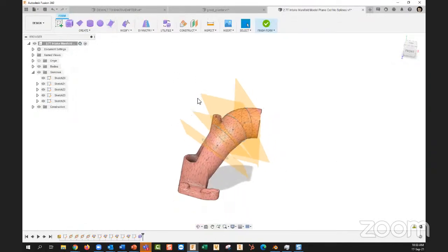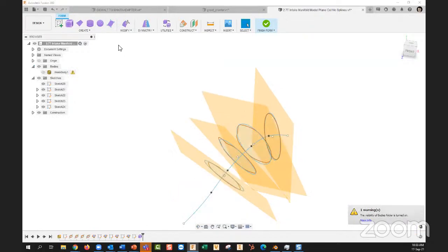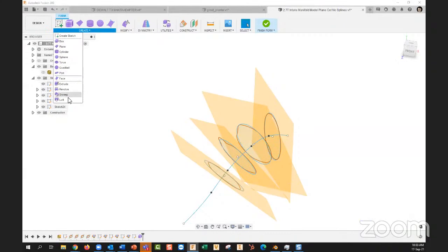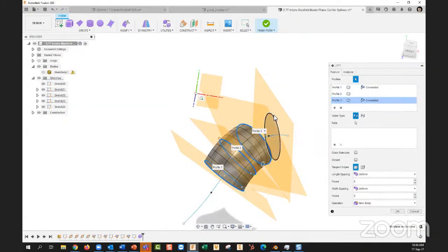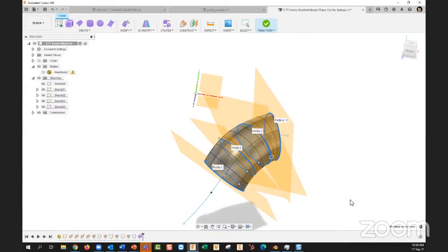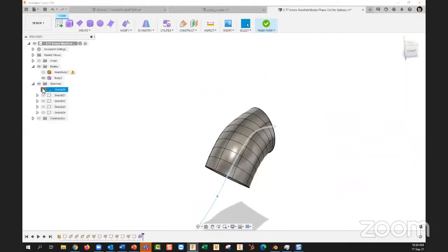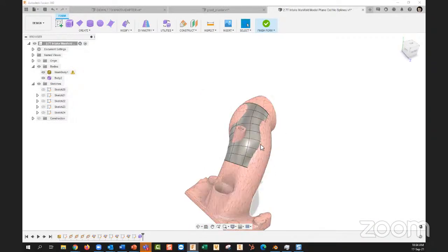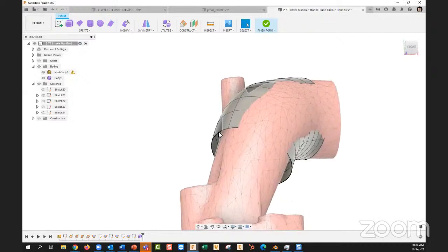And then instead of lofting it with a regular loft, let's go ahead and loft it with the T-spline loft because you can move that around later. Loft, let's go 1, 2, 3, and then 4. And now we have this sleek looking T-spline body, which is similar to the original mesh body. That's definitely off right there.